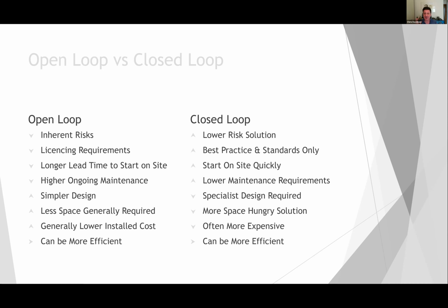However, if you've got a nicely balanced heating and cooling solution, where you've got heating and cooling loads going on either simultaneously or interseasonally, then you can actually manage a closed loop temperature to optimize efficiency in the way that you just simply cannot do with open loop, particularly if you've got any groundwater movement going on there. So any heat you're storing in the ground could get washed away. So there are differences. It's complicated, and so in order to model those, it's very important that you really seek expert advice if you're getting involved in these systems.